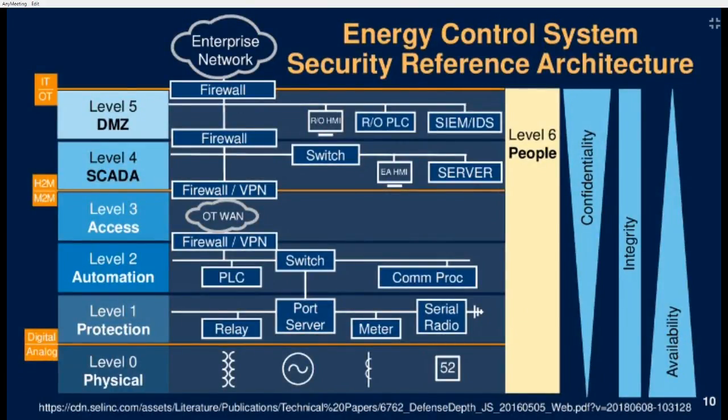It is very important to segment OT from IT, creating a DMZ between OT and IT for information that may be required by IT to do their job, and then segmenting human-to-machine traffic of layer 4 from machine-to-machine traffic of layers 1 and 2. In layers 4 and 5, you have workstations and servers that require much higher confidentiality and should be operated, maintained, and secured much the same way that you do in an IT network.